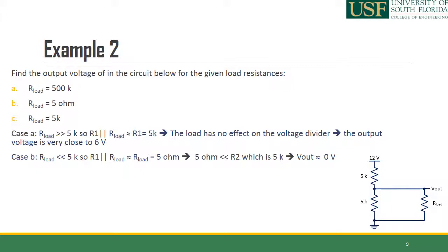If you recall, we had the rule that if the resistance of R1 is much smaller than R2, we know that the output is almost 0. You can try to put the numbers into the equation, and you will learn that 0 volts is quite a reasonable value to be considered as the output of such a circuit.